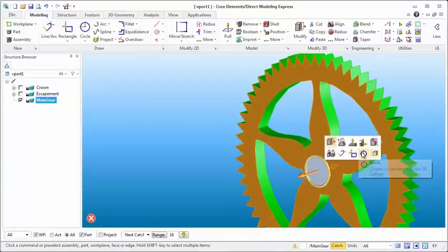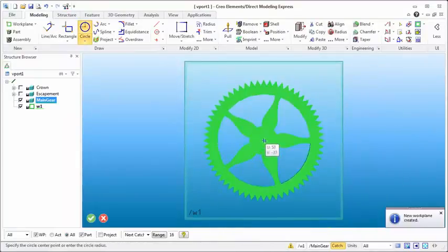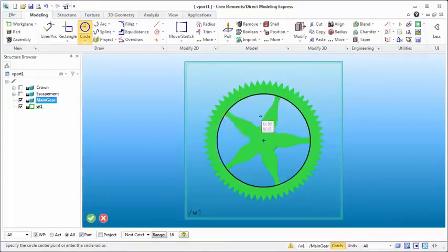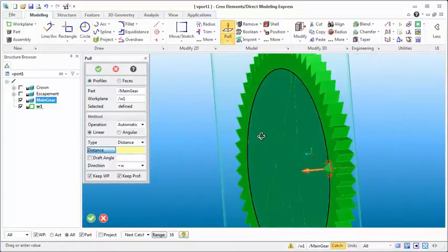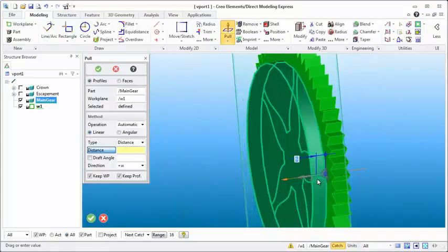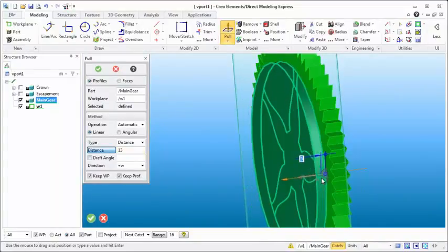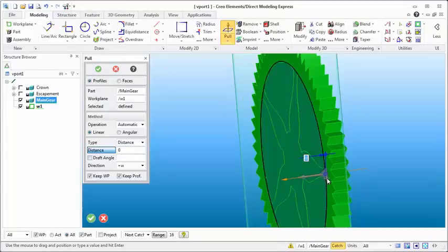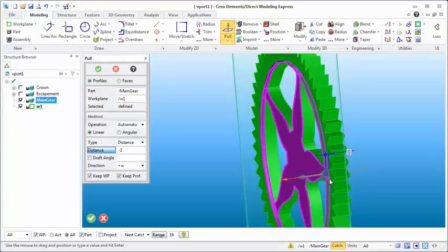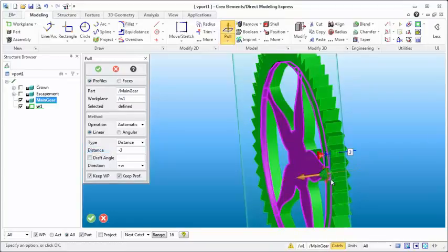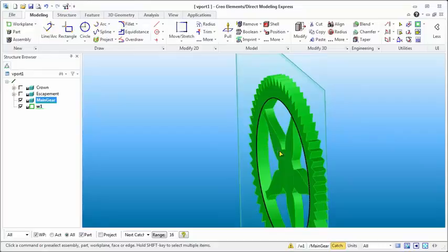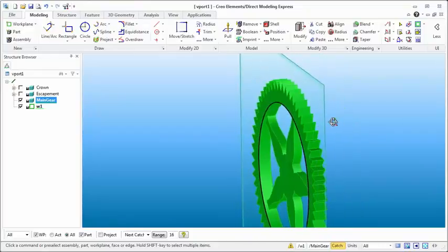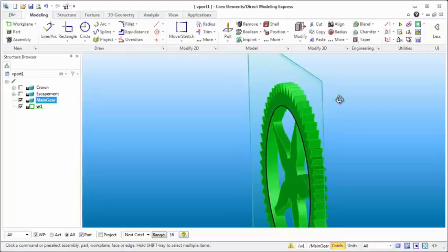At this point, we can come in here and start sketching. I'm just going to hold down Shift, grab the center of that circle, then I'm going to come out and hold Shift just to get to that point. And very quickly I've established that circle that I need. And I want to take him, and instead of pulling him out, I want to use him to cut in. You'll notice that it will make a boss if you're coming that direction. It'll make solid. But if you start going into the part, it starts cutting. So let's just go in, 3 looks pretty good, and we'll say that that's okay. So we've made that initial cut, and that's great. But what if I want to make that cut on the other side? Do I have to come over and redraw everything, recreate another work plane and everything?